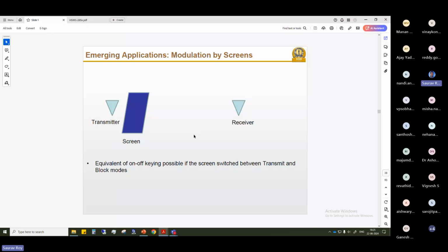And the other topic we have studied particularly in our lab, our group, is called MBM or media based modulation. So what happens? Why media based modulation? Media is nothing but the environment through which the wave propagates. And by changing the media itself or taking advantage of the propagation through the medium itself, we create the received signal or our received constellation at the receiver. That's why it's called media based modulation.